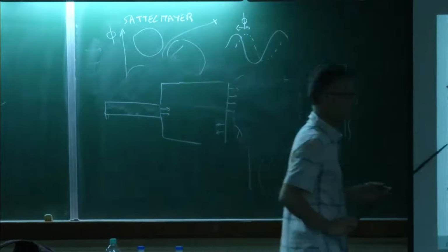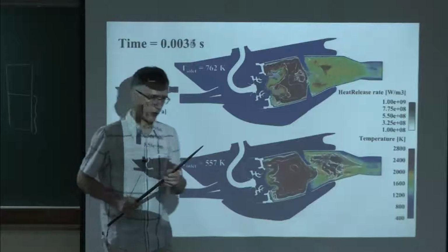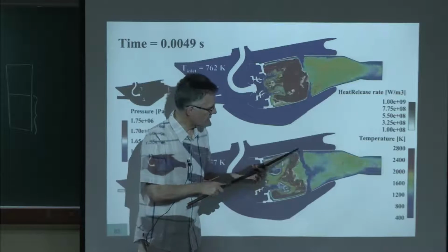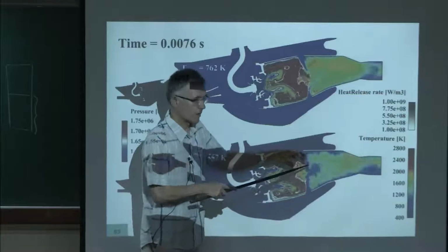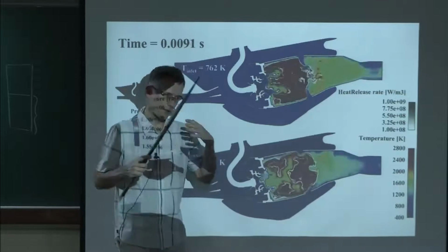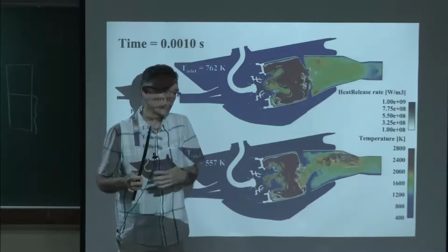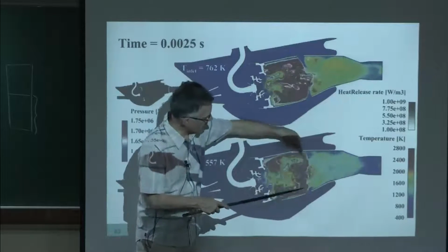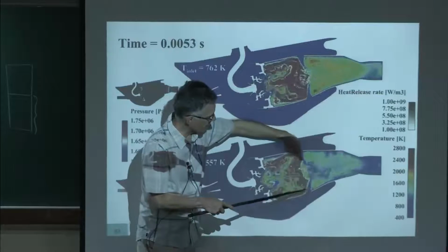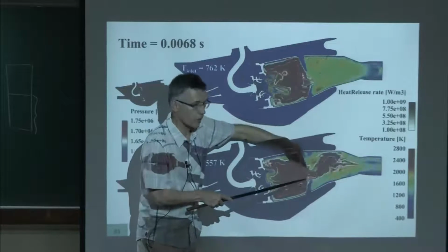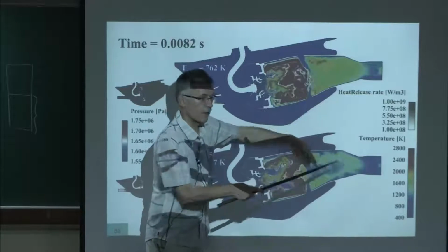That's interesting actually. That was connected to what Professor Kuchari said yesterday. What we see here is that it's really the secondary jets which cut these pockets. And he was interpreting that in one way. I'm seeing it in a different way. I believe that these jets are what's actually creating these pockets. If the jets here are intermittent, you have a hot jet and a cold jet. If they are intermittent, then you create entropy waves.